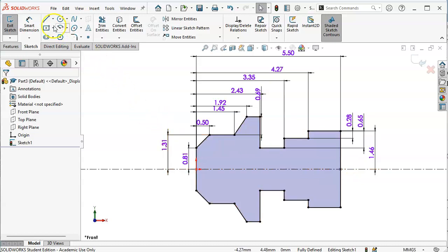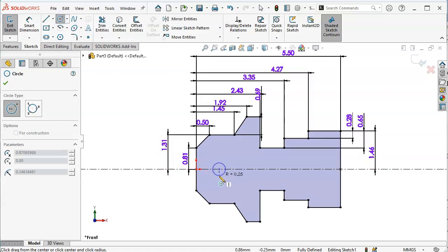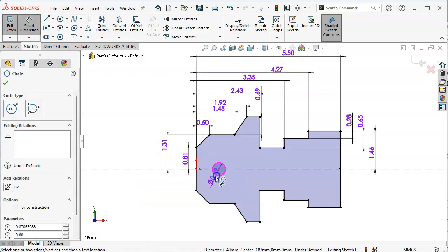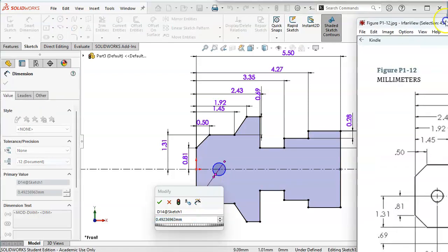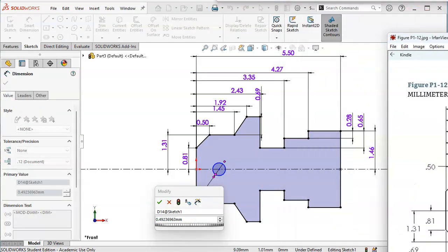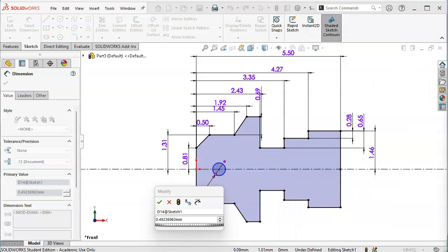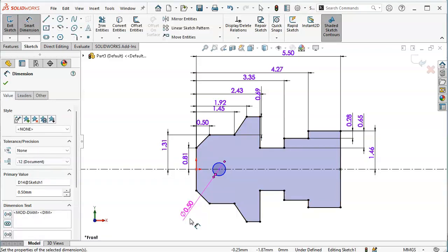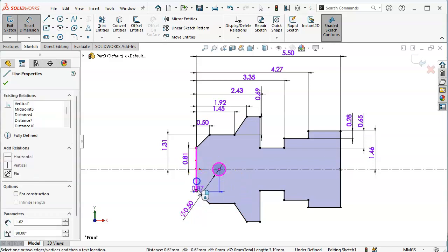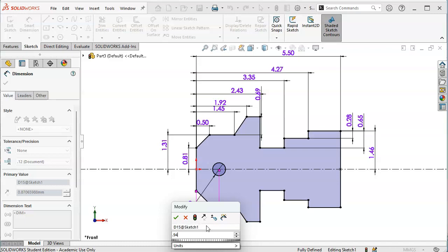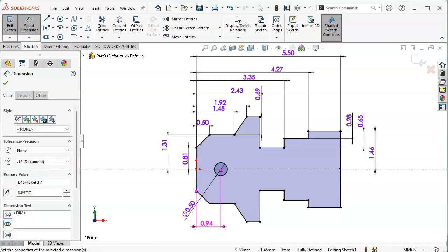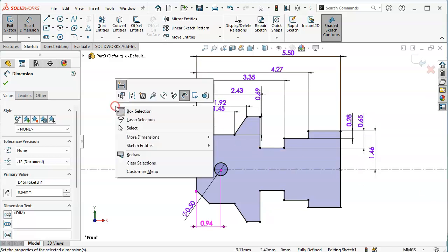So let's go ahead and put in the circle, and I will dimension. All right, let's get some numbers, 0.94 and then 5 times the 0.75. So that was our half-inch dimension, and since I clicked out of it, I'm just going to click once in that selection box, 0.5, enter. I should still be in dimensions, so I can put in the 0.94. All right, and then 1, 2, 3, 4, 5. So they gave us the spacing, but we're going to have a total of 6 instances.